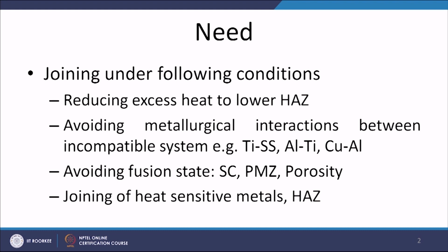in order to reduce that, reducing the excess heat so that the heat affected zone size can be reduced, it can also be used under the conditions when metallurgically incompatible systems are to be joined. Then the solid state joining processes can be used. For avoiding the metallurgical interactions between the incompatible systems, such kind of process can be used,